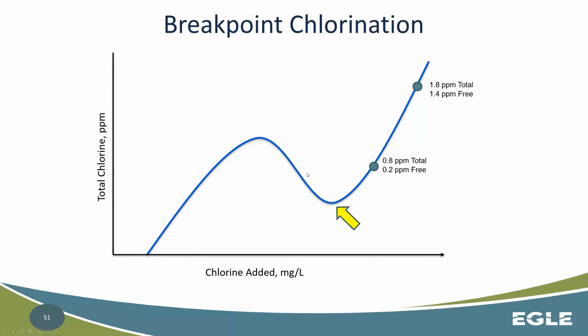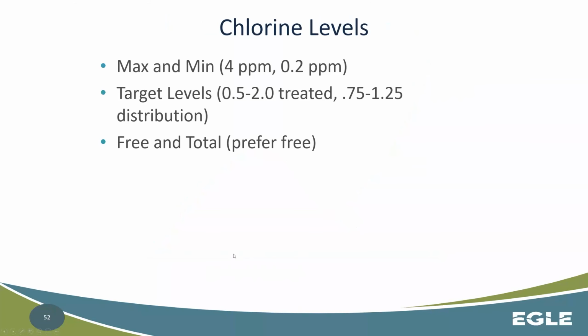But that also comes down to where you're at on this breakpoint curve. If you get beyond this breakpoint curve and you're in that area up in here, this is when you're going to get very good disinfection, and on top of it, very low odor complaints.